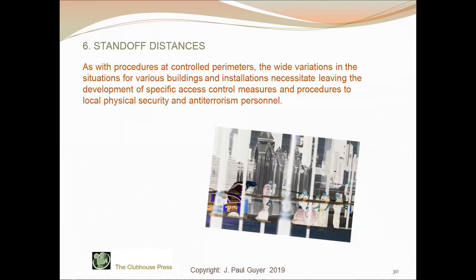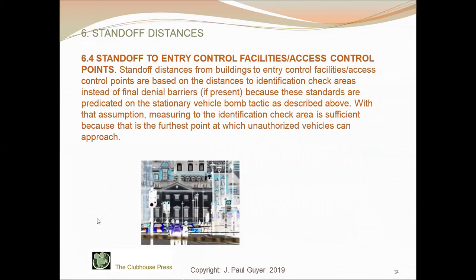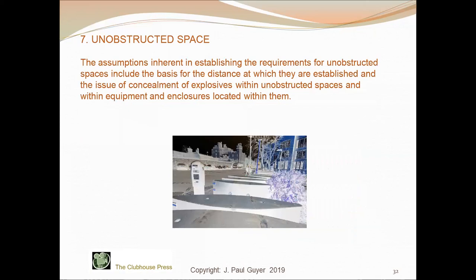Now, of course, the term hardening of a building means additional structural features that you retrofit or incorporate into your building over and above those that are required by conventional building design for static loads, live loads, dead loads, seismic loads, wind loads, that sort of thing. Additional strengthening.